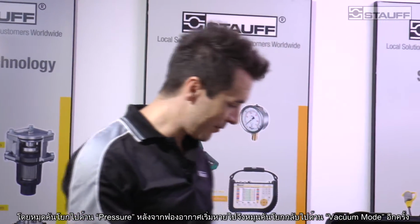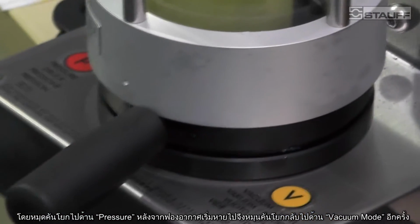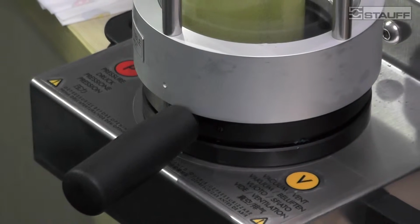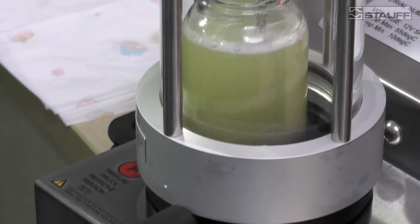If you have too much foam, maybe you have to vent the chamber once, make sure the foam escapes, and start again. This process can usually take 30 seconds, minute or two, depending on how thick the oil is, or depending on viscosity of the oil. High viscosity oils will take longer, low viscosity oils will take shorter time to remove all the air.